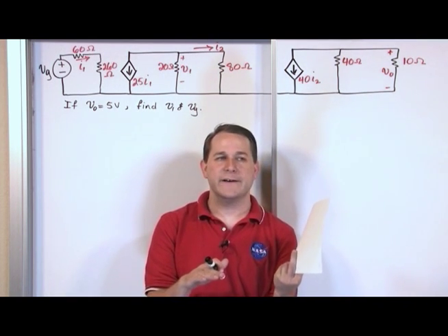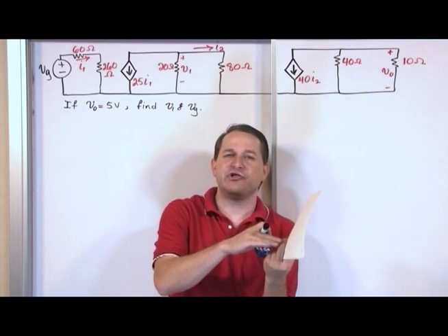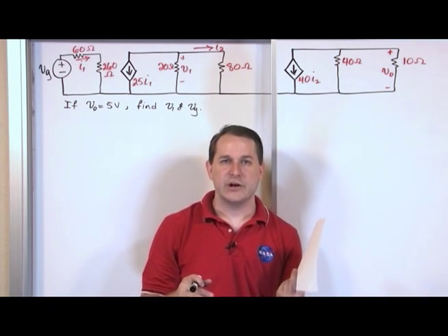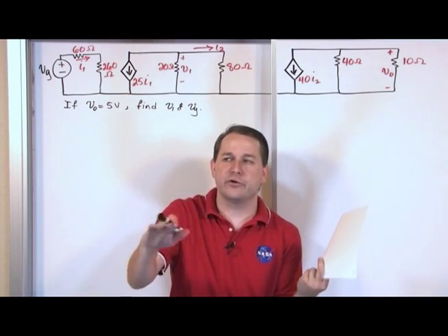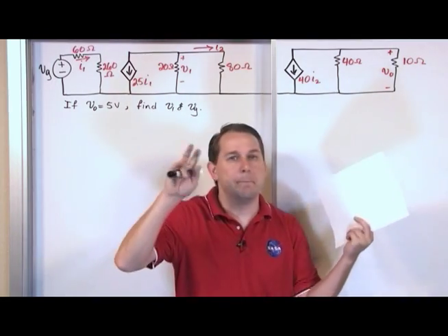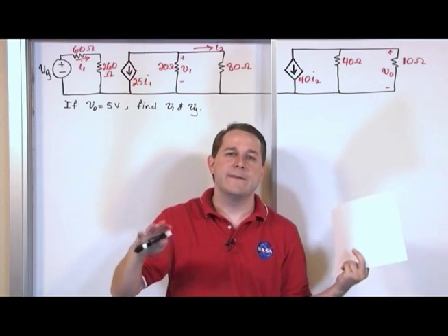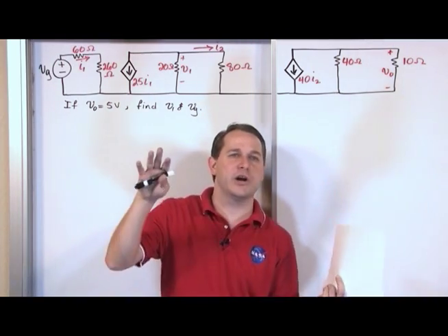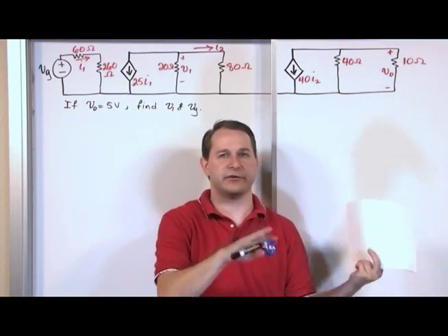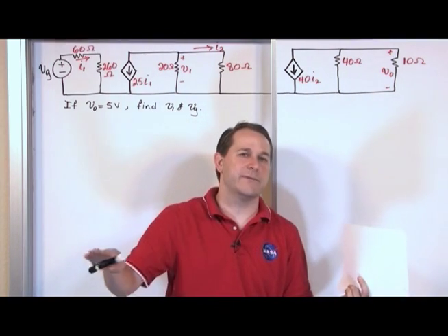In other words, since voltage is a change in potential, then you want all of those circuits to have as their base voltage, the bottom of their mountain, so to speak, at 0 volts, let's say. And then that way you don't have any discontinuities in the voltage from circuit to circuit to circuit. You want them all to be on that same level playing field.